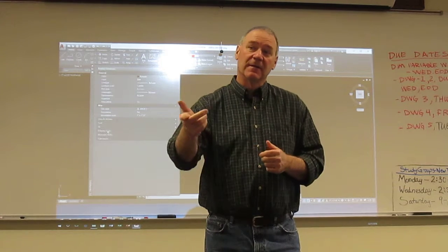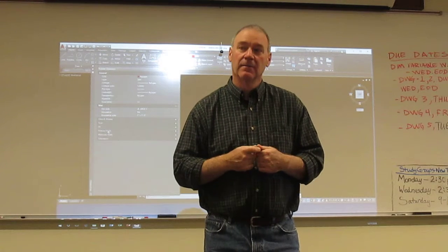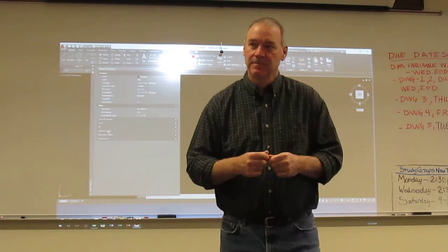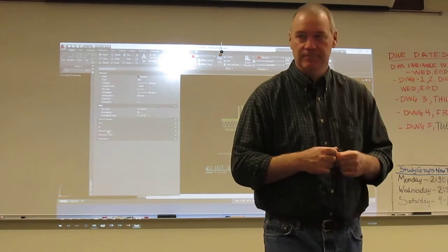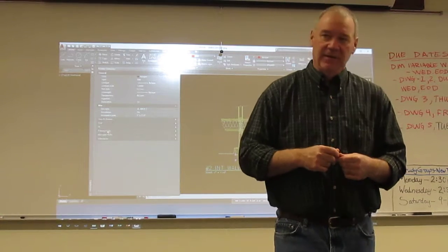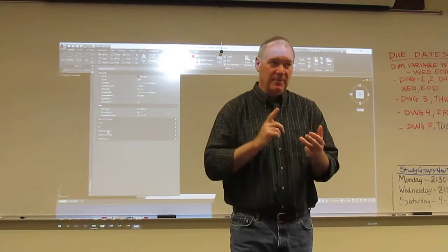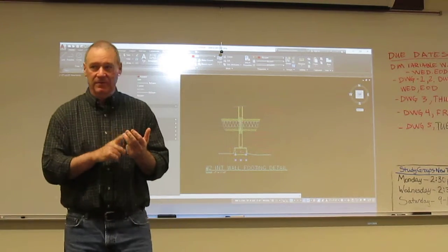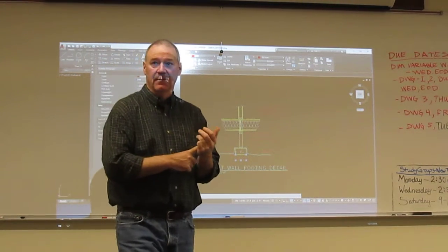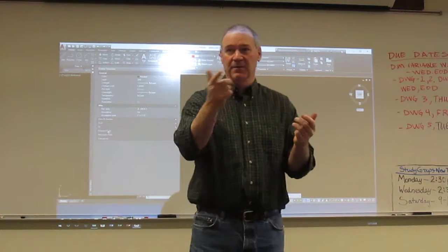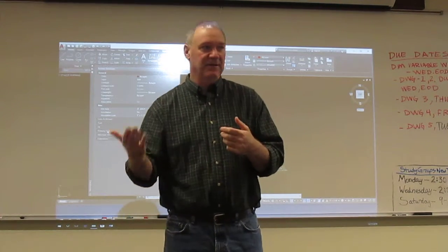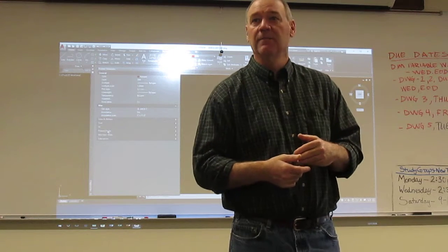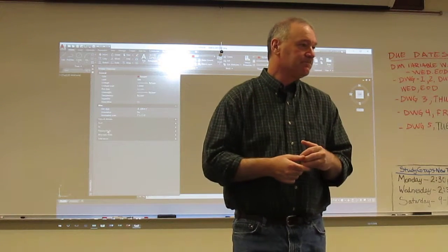Did that answer your question? Yeah. I was mainly wondering what chapters, because it would have sucked if I had to look through all the chapters. Really, the only thing that probably won't be on there is 19. We only had the primary units tab, although there will be some variables I'm going to cover off of that tab, because there's DIMLUNIT, DIMDEC, DIMZIN, DIMAZIN, DIMADEC that we use quite frequently.